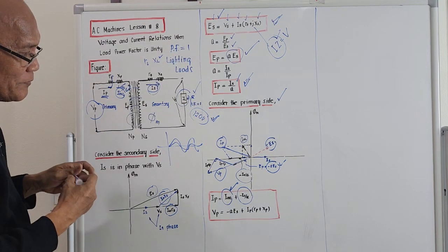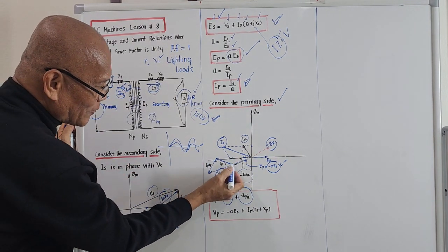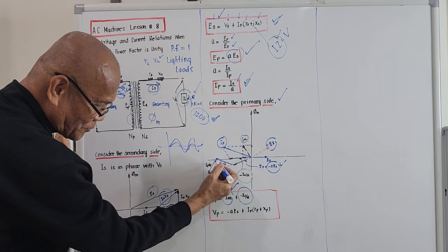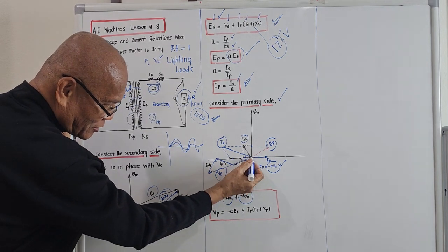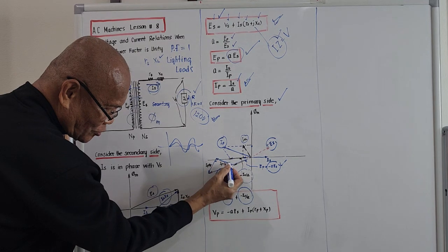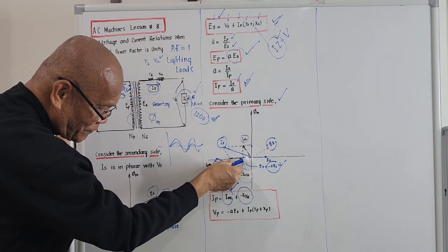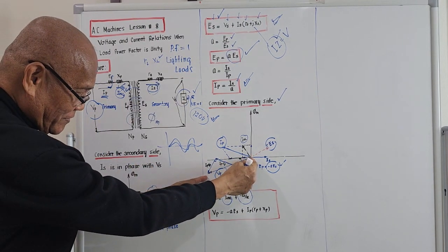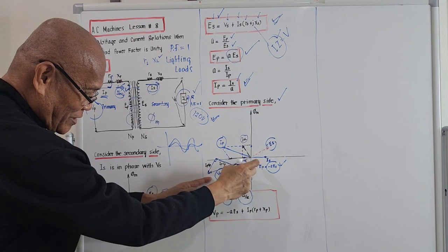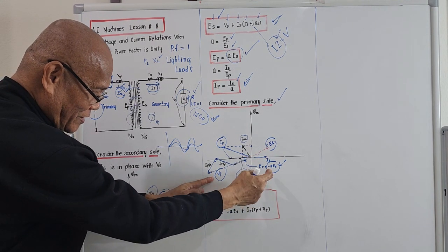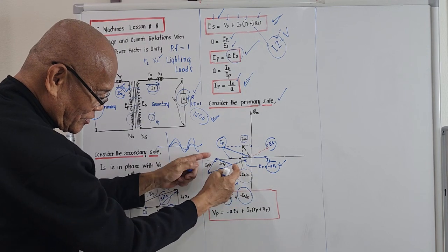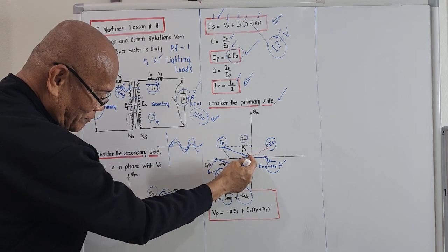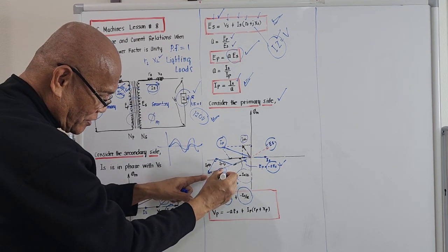So it is represented by this. This portion is the product of IP, RP. It is perpendicular to the value of IP, XP. So the vectorial sum of this negative voltage here, plus these two impedance drops, is actually VP. VP is this one, the largest thing. Right? So this is the primary induced voltage due to the secondary load. This is the impedance drop for the resistance. This is for the reactance. So if we add vectorially these three things here, it represents VP.